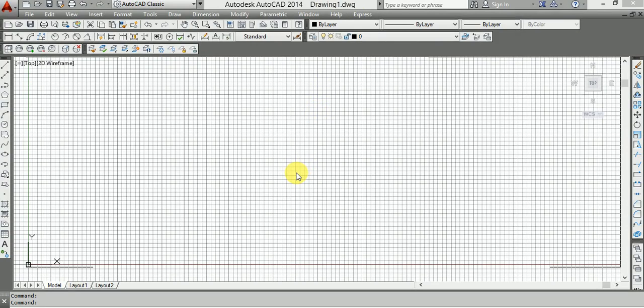So to prepare the workspace for your drawing, if I go through the previous commands, let's start like that. At first, we want to change the background color if needed, because if you start the software, it may show the black uniform background. You need to change that because we always print the drawing on paper, which is white. Using the same workspace setting will help you to better understand your drawing.